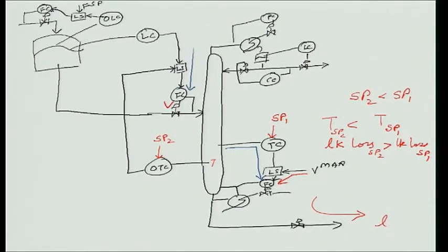Now ordinarily, this is how things would go. The feed to the tank, or the feed to the process, is set by the operator. Now let us say the instruction comes, jack up throughput, and he keeps on jacking up the flow set point, and as the flow is being increased, the boil up becomes max.